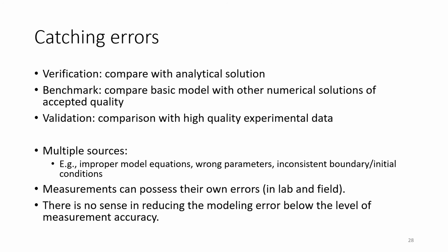The difficulty here is that we can have so many different sources of errors. It can be very fundamental, in terms of a modeling error, that you do not apply a proper model for the question you're studying. It can be that you made a mistake in the parameters, used wrong units, or formulated inconsistent boundary or initial conditions. There are so many errors you need to consider and find out, and it's an iterative process to come up with a good model.